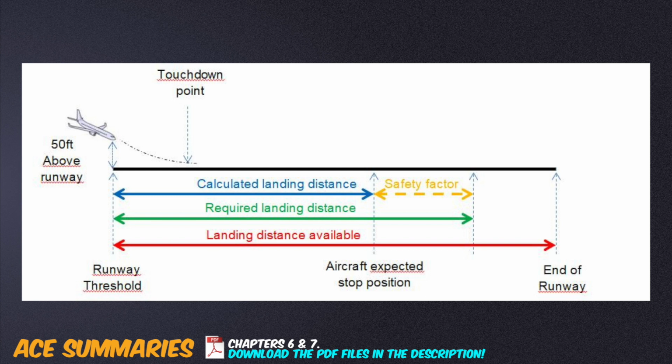VMCL is the minimum air control speed in the landing configuration. VAT is the velocity at threshold. It is more often referred to as VREF and often corresponds to 1.3 times the VS. A pilot must ensure he crosses the threshold at this speed to guarantee the calculated landing performance for that field, especially if the runway is tight in length.